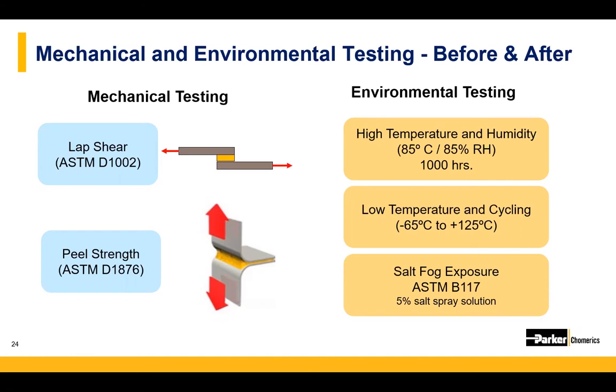Low temperature testing is also done to make sure materials will operate after low temperature storage and in cold environmental operation. This is important for all kinds of military applications, such as high altitude and shipboard programs. And after environmental testing, the parts are all run through the same transfer impedance, shielding effectiveness, and mechanical tests, and those values are recorded.